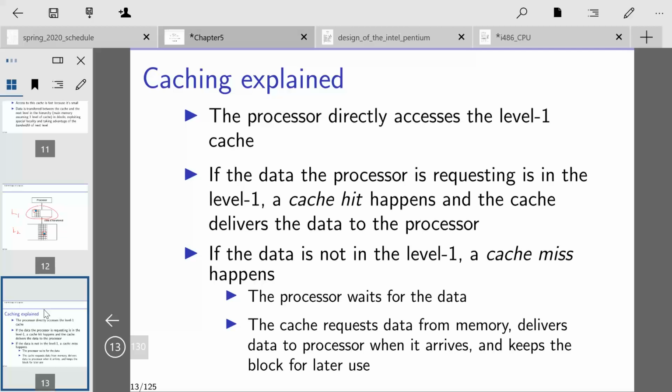Okay, so then it'll go through the DRAM controller and access it through DRAM. DRAM is so complicated it has to have its own controller. So when you look at a die shot, where they break the die up into different parts, you'll see the processor, the different levels of cache, and then usually on the perimeter of the chip you'll see a DRAM controller, and of course that's because it's very I/O intensive to communicate with external DRAM.